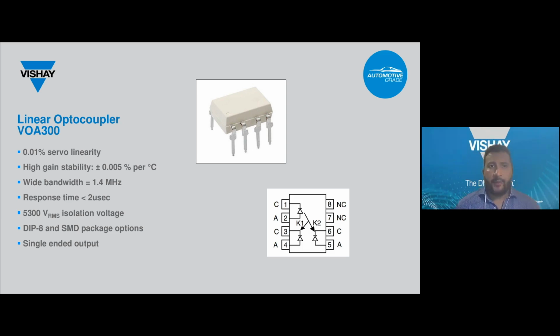It offers 0.01% linearity and high gain stability over temperature to maintain a very precise voltage measurement as it passes across the isolation barrier. The 1.4 megahertz bandwidth and less than 2 microseconds response time give a high-speed response. This optocoupler is rated at 5300 volts RMS for isolation voltage with either a DIP8 or SMD package.